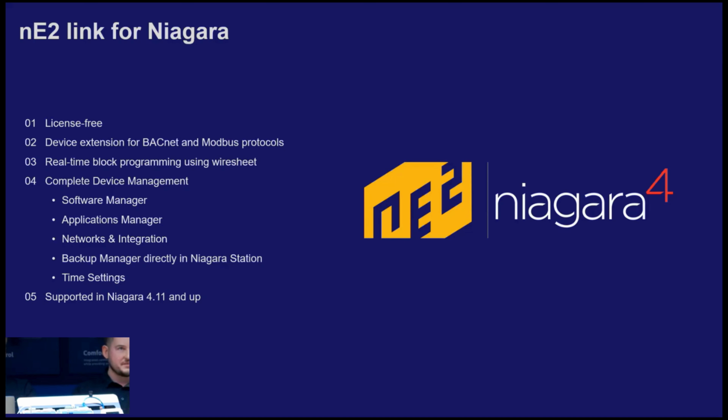First of all, it's license-free. You don't need to do anything related to licensing the module itself. You just need to download it from our IC Connect application. It is an extension for devices in both BACnet and Modbus protocols, which means when you download the module, you will just need to open the module palette and drop the NanoEdge device extension onto one of those networks in your Niagara Workbench.